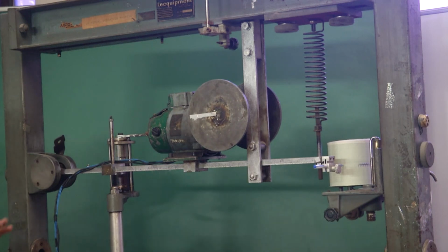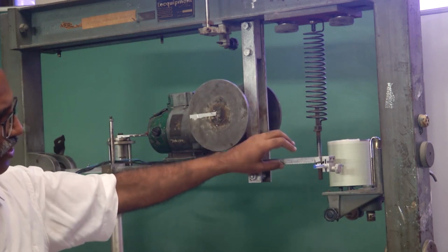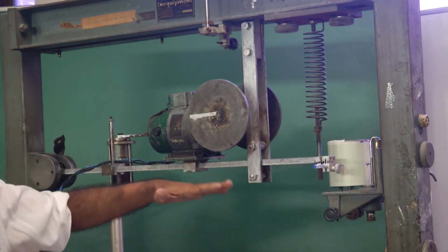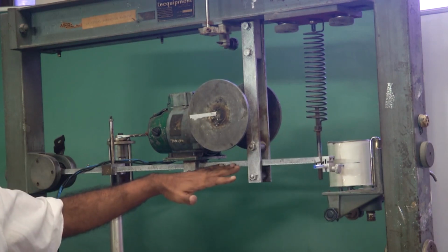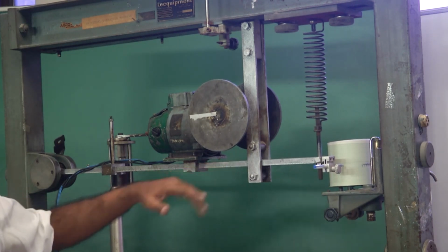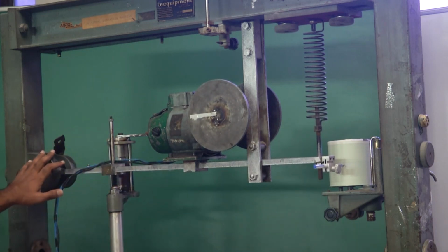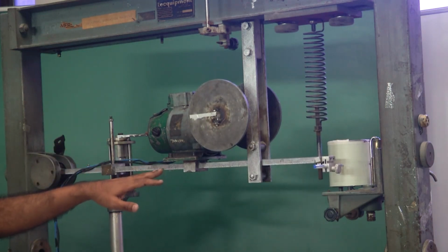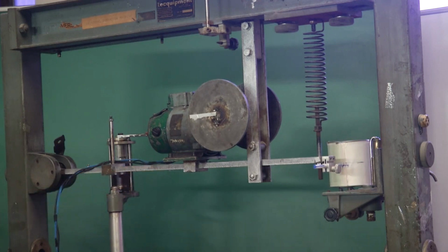Now, one source of damping is structural damping. If this beam deflects and undergoes strain, that cyclic stretch and compression in the beam is going to cause structural damping and dissipation of the vibrational energy. But in this case, as we have seen, there is almost a remote chance of the beam actually bending and generating strain.